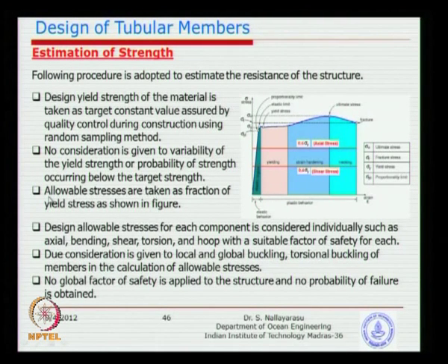allowable stress design. So, you see this diagram, you can see here there are two red color marks drawn there. One is having a shear stress of 40% of the yield, the other one is axial stress of 60%. Now, if you ask why we have got this disparity between shear and the axial, basically shear has no distribution, whereas at least axial can have some distribution depending on the combination with bending, but bending has larger distribution, like we saw in that bending moment diagram, we could actually possibly increase the load double just because of the triangular distribution, to 1.5 from triangular to rectangular, and basically that is.